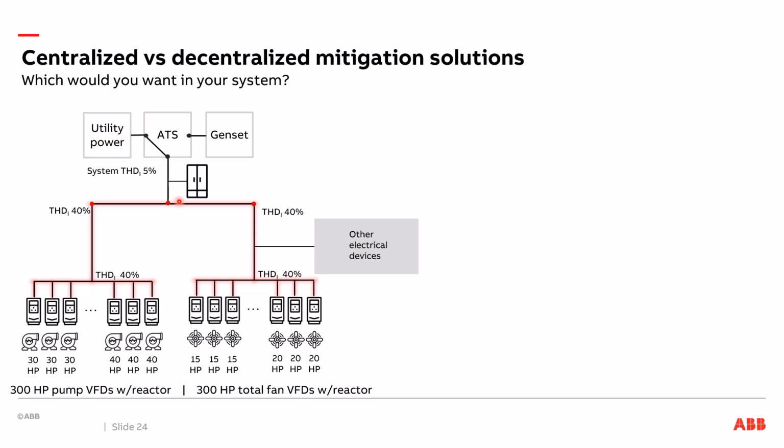You will have, though, a little bit of voltage distortion being generated and fed over to these electrical devices, because what happens is with current distortion creating voltage distortion, you still have all this current distortion working its way up through the network. So depending on the lengths and the impedances and size of these wires, that all is one of those variables that impact how much that voltage distortion is. There's really no way for me to answer that because there's just too many variables in the system.